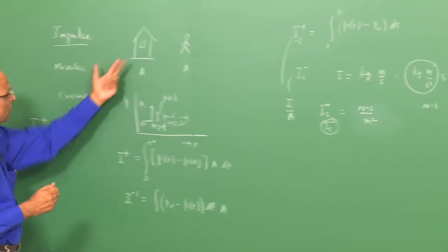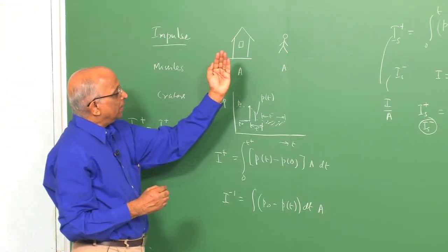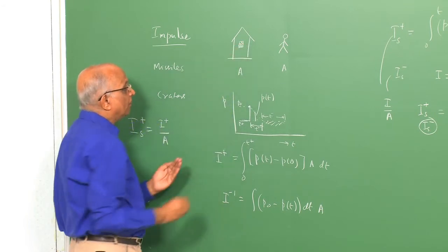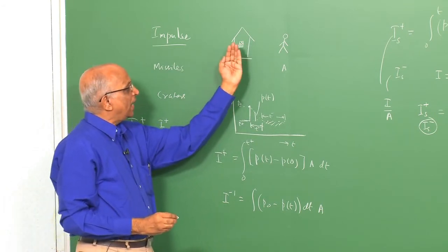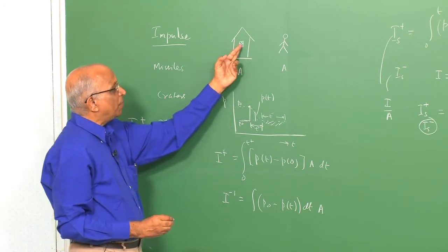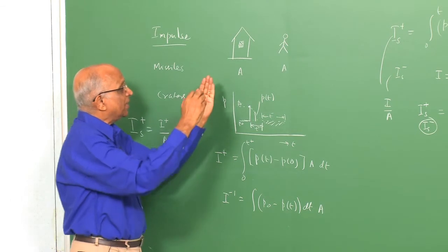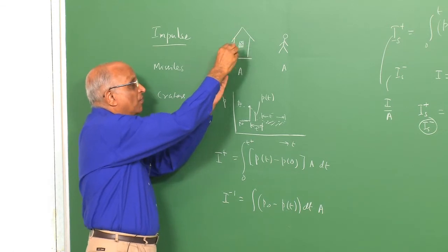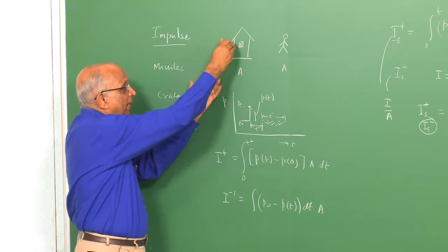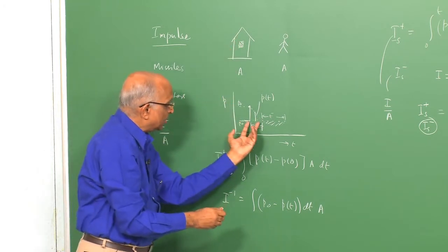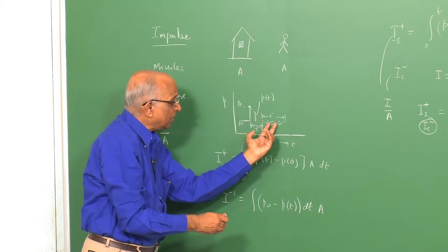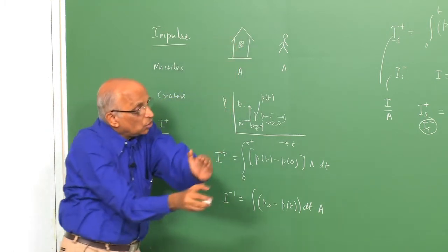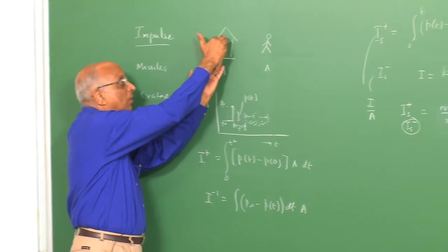Let us take this example again of the house. Let us say I have the blast wave coming, hitting this over here. Let us say this is the window pane of this house, which I now show here. Because of the impulse and the sudden rise in pressure, let us say that the window pane gets shattered. Initially the impulse is acting in this particular direction towards the house, but it takes some time for the window to break, and when it breaks, the window is subjected to the negative impulse. Therefore, the fragmented part of the window falls towards the explosion site rather than falling inward, along the direction of the explosion.